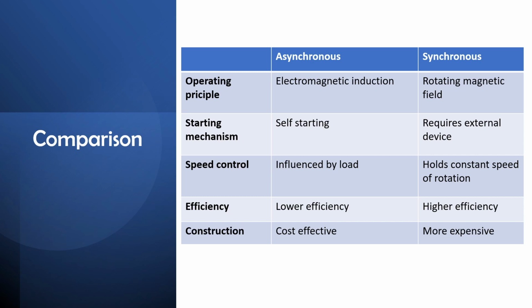The synchronous motor is an electric motor which operates by synchronizing the rotation speed of its rotor with the rotating magnetic field in the stator. The motor is powered by alternating current in the stator coils, generating a constant speed rotating magnetic field. The rotor, equipped with the permanent magnets or windings, aligns itself to match the speed of the stator's magnetic field, resulting into a continuous rotational motion.